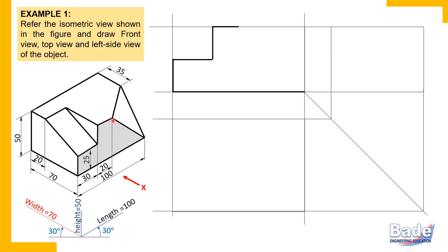Remember, non-principal edges are to be drawn by connecting their ends. You will get the ends of that edge first. So watch here, this principal edge, its right side end, that is this end, and the right side bottom corner, this corner, you should join. So this is that inclined edge. So we have completed the true shape of this surface. Remember these edges, and actually only these edges we have drawn here. So no intelligence is required. Just be very careful in measurements.